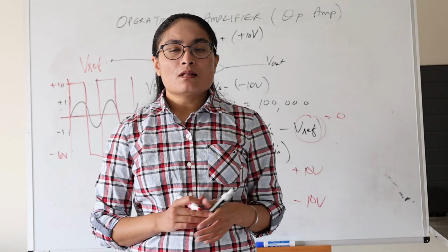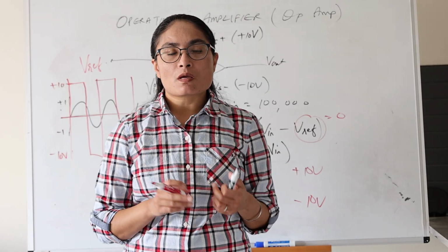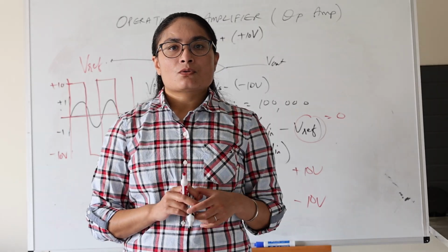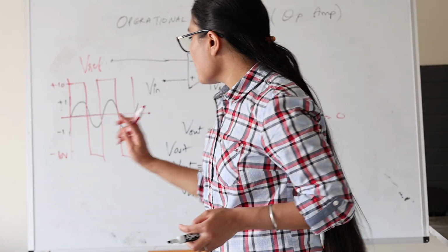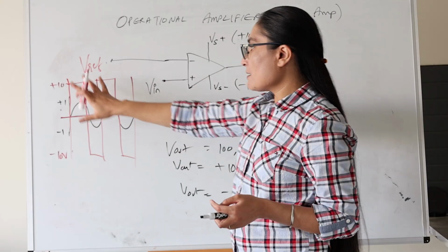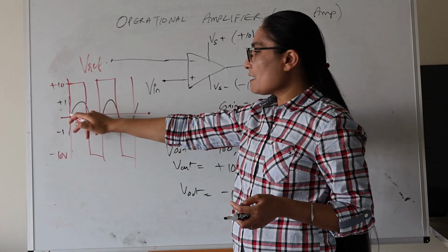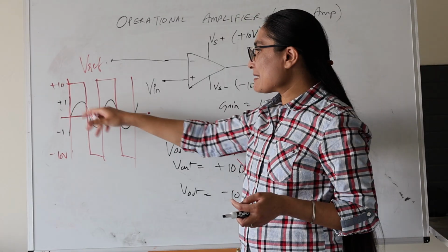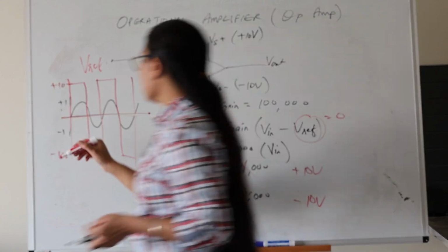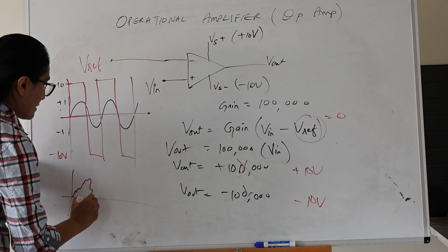This is pretty simple. And one thing that you can learn beyond this is a Schmitt trigger circuit. So one thing to note here is, even though the math works out and it gives us what we want, in reality the input signals are not as clean. The input signal can look a little bit jittery, something like this.